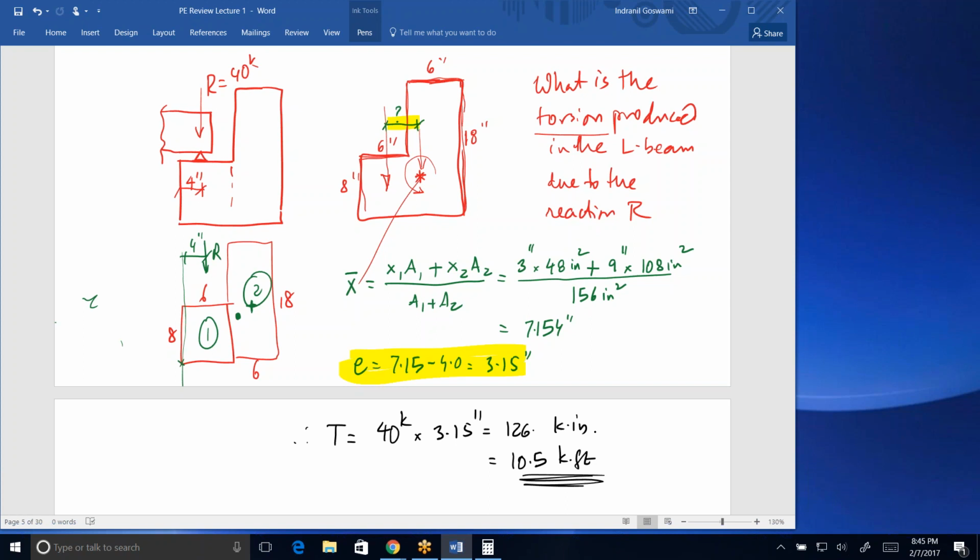The best example that comes to my mind right now is one of these wastewater treatment things, where you have these rotating discs where the wastewater comes in contact with the microorganisms on the surface of those discs. But in that case, both surfaces are in contact with the wastewater. So the area in that formula is actually the total area on both faces of that disk. So if you calculate pi r squared for the disk, if the full disk is submerged, that is, usually it's not fully submerged, but if you're calculating using the circle formula, you're only capturing one side, but you have to then double it in that particular situation, right?